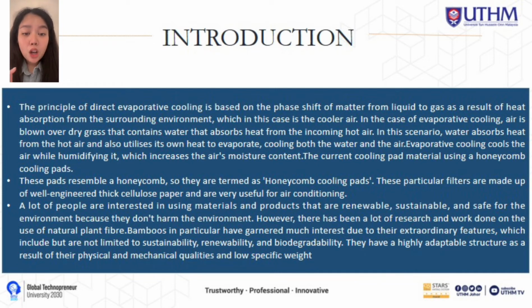There are many factors which affect the efficiency of the evaporative cooling process, such as the surface area and thickness of the pad, the material of the cooling pad, perforation size, air flow rate, inlet relative humidity of the air, volume flow rate of the cooling water used, inlet water temperature, and etc. Out of the different parameters listed above, the evaporative cooling pad material is an important parameter on which the performance of the cooler depends.